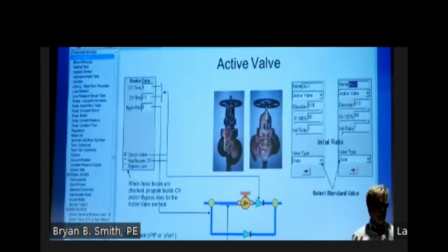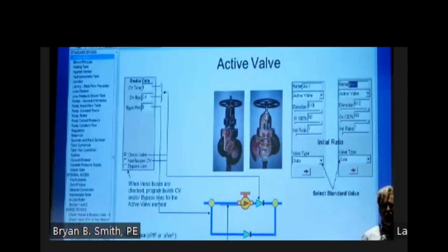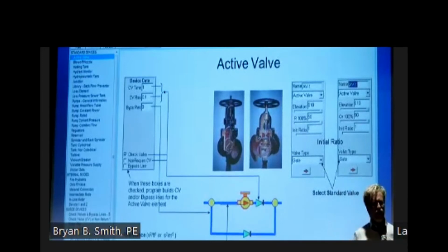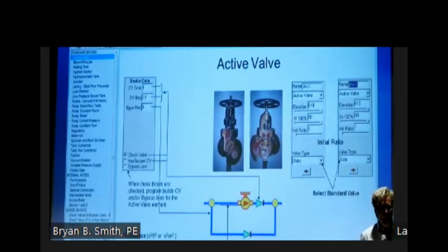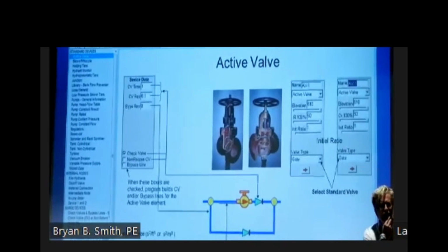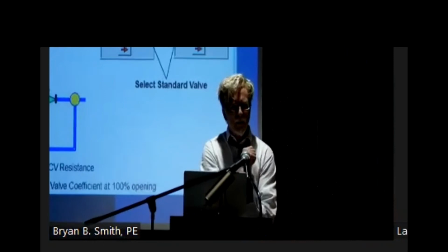And you're like, well, isn't that normal? That's in our design. But coming into that chemical plant, I have a reduced pressure backflow assembly. I'm flowing 1,000 gallons per minute. And then I stop. Guess what happens? Kapow! That pressure in your water system might go from 40 PSI to 400 PSI. So your municipality, and this is your client, they're like, God, I don't know what's wrong with this system. And it's that customer that's destroying the municipal water system.